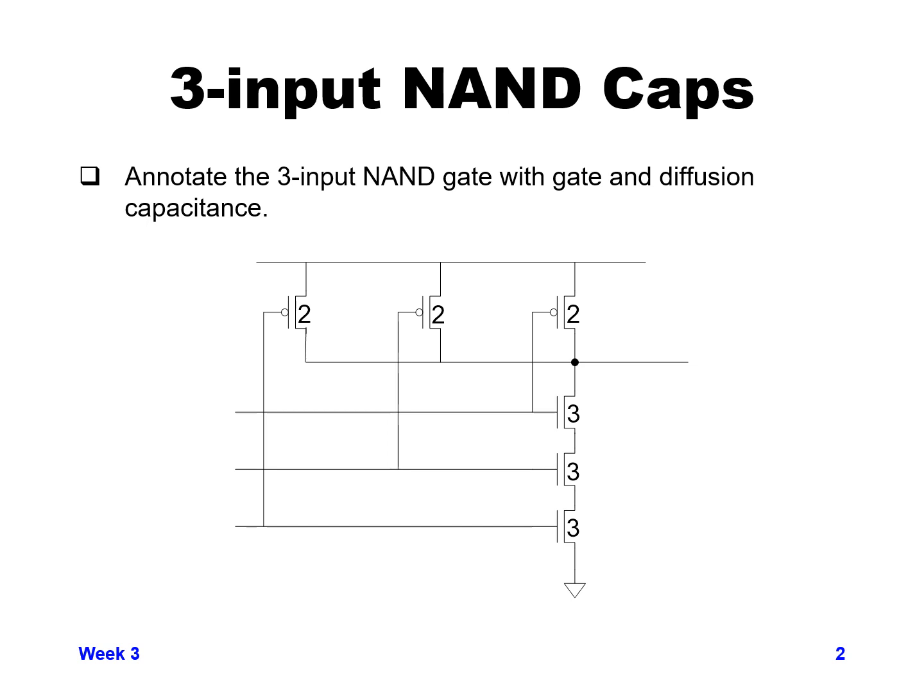After sizing a 3-input NAND gate to give us the pull-down stack, if the full pull-down stack is on, the equivalent resistance in our model from output to ground is going to be equal to if we had a single size 1 NMOS.